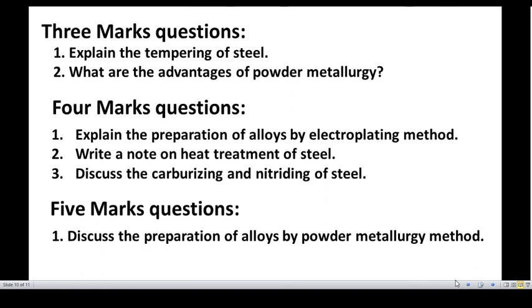After obtaining the required alloy, it is extracted from the lower die through an extraction pin. So the instrument consists of a lower die and an upper die, which are held together by guide pins, and the lower die consists of the molding cavity in which the powder mix of the metals is taken, and a high pressure from the upper die is applied on the material taken in the molding cavity.